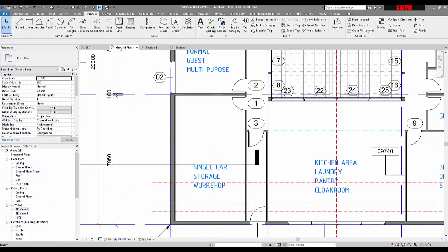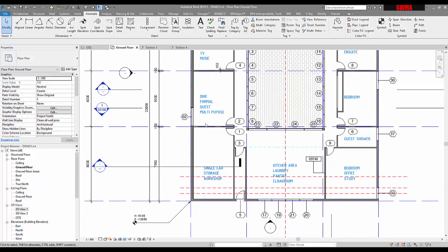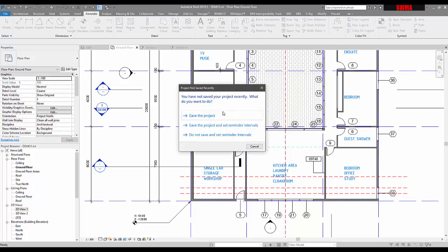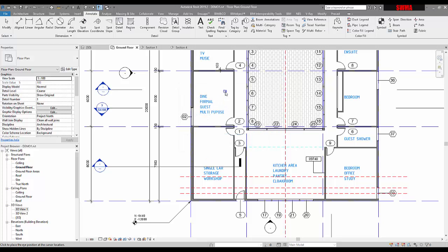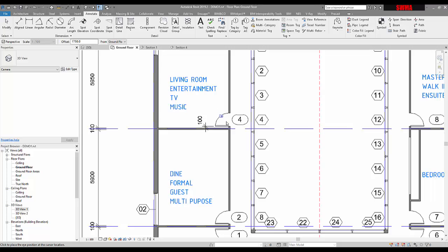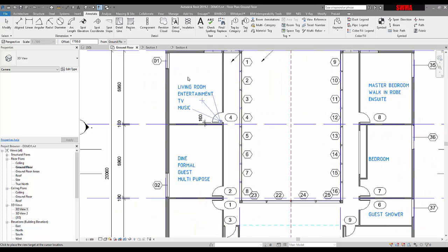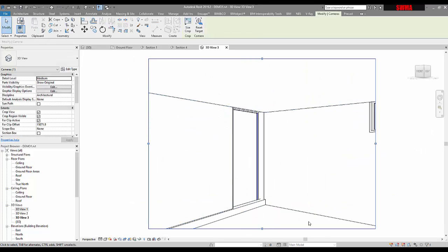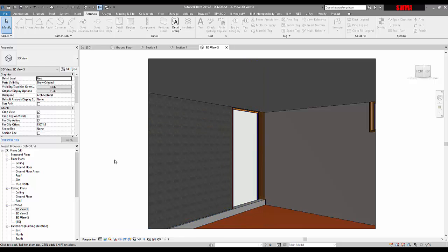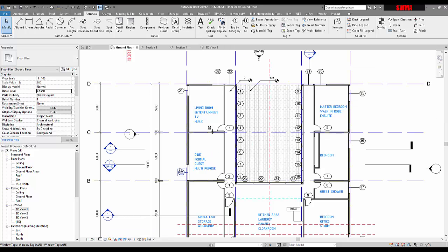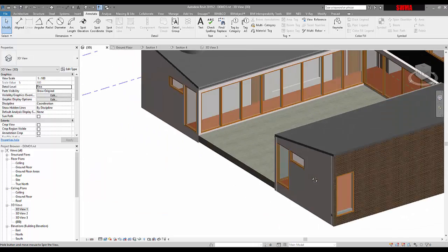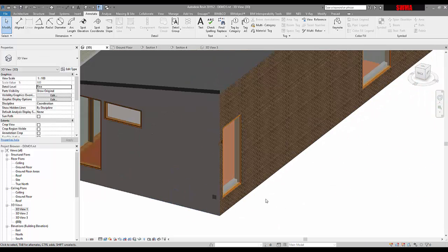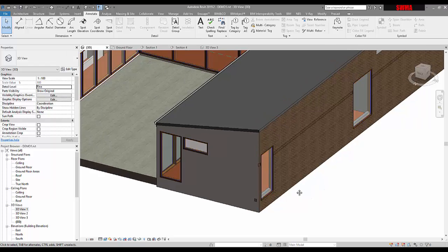If I go to my floor plan view here, and we want to see the skirting inside of that space, I can go to a camera view, and I will grab this view here. So I'm just standing inside the door. What does it look like from the inside with the plasterboard? Here it is. Go fine, realistic. And so this is the component of the wall with the sweeps and reveals, very basic.